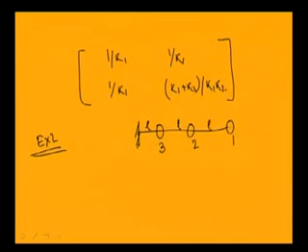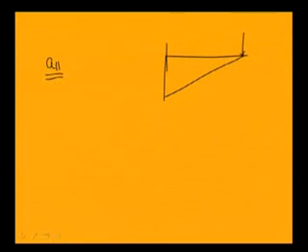As I am applying a unit force here, the bending moment at this position also becomes 3L. So this bending moment is 3L and this length is also 3L, and I have to find the displacement at this position by the area moment method. This is equal to the moment of the area of this by EI.